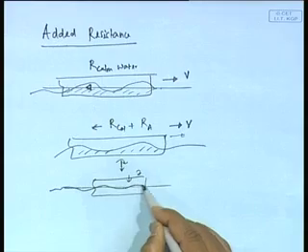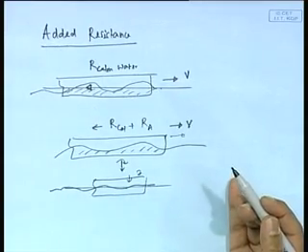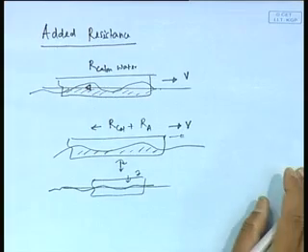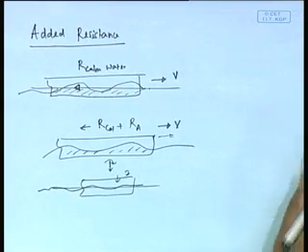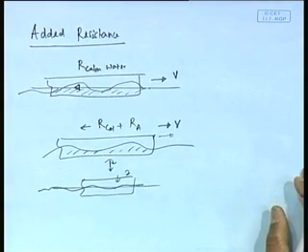So, what is happening is that these obviously show up as additional resistance. See, when my ship is going in calm water, it is making a wave resistance wave, a calm water wave. But now, on top of that, my ship is also oscillating, and if I do that, it is going to cause further waves, because any body in calm water, if you oscillate it, will create waves.